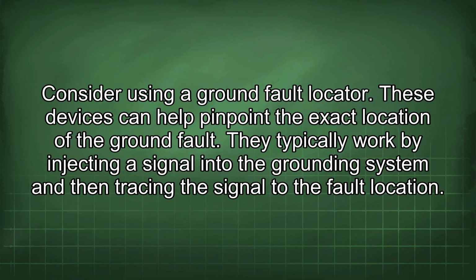Consider using a ground fault locator. These devices can help pinpoint the exact location of the ground fault. They typically work by injecting a signal into the grounding system and then tracing the signal to the fault location.